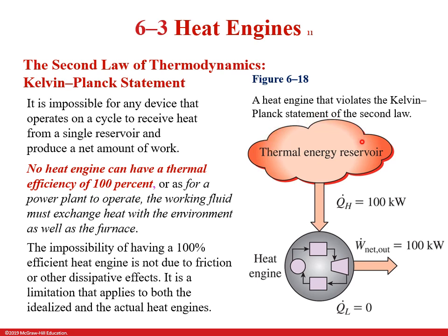You've got a thermal reservoir, you're transferring 100 kilowatts of heat, and you're getting 100 kilowatts of work out, and there's no heat transfer to the environment. This is an impossibility. This is a violation of the Kelvin-Planck statement. You need to dump heat to some reservoir.